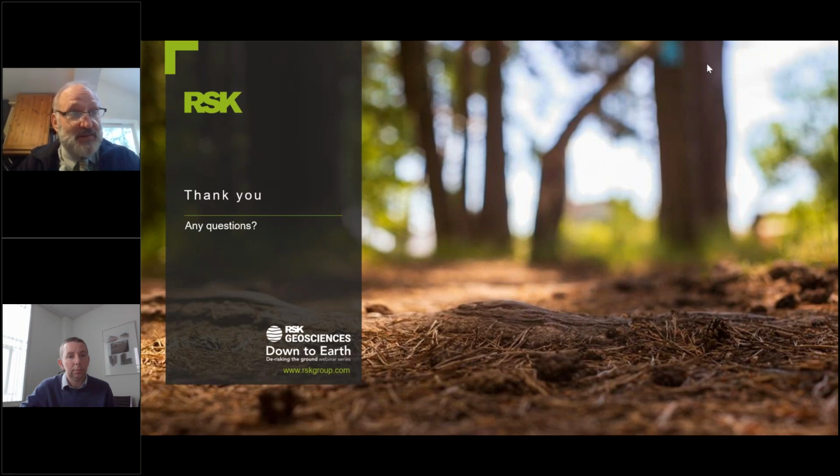Within their revised 4.6, they mention that if you've only got loose supervision on the site, then they will require a more onerous form of foundation than if you've got a high degree of control, a high degree of testing, and so on. There is a graded foundation solution. They'll require more effort put into the foundation because they haven't got the same confidence in the control being exercised on site.